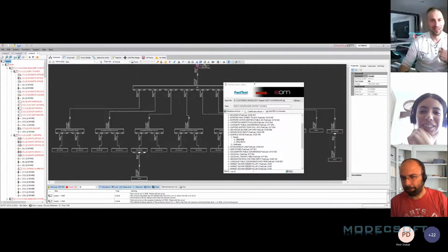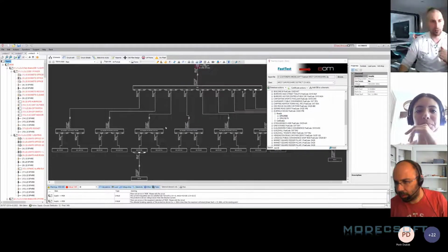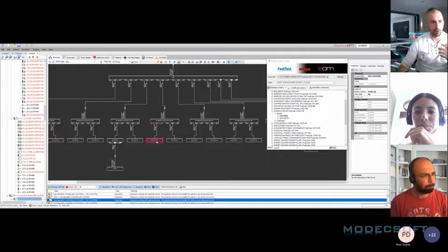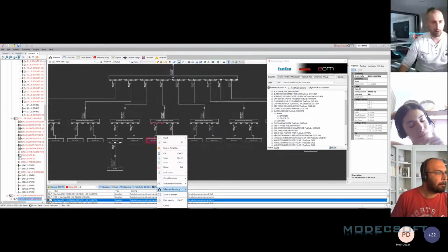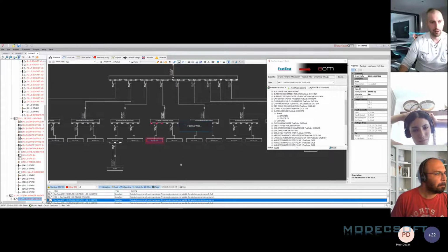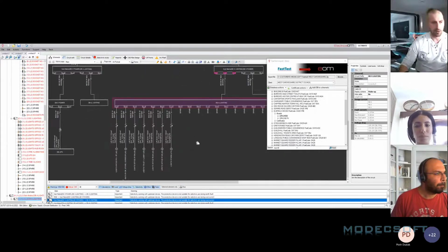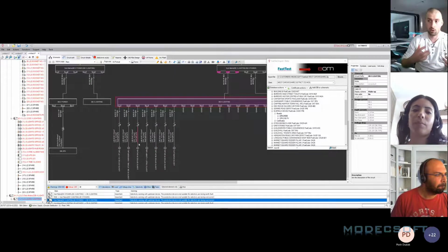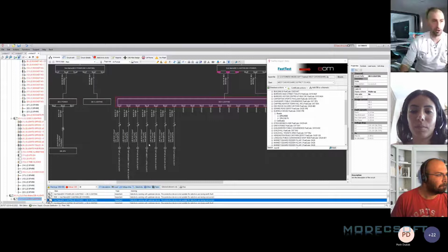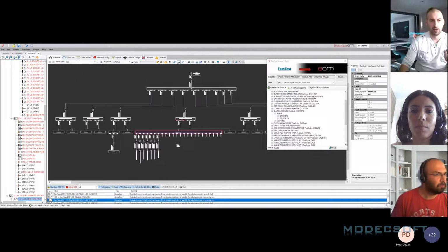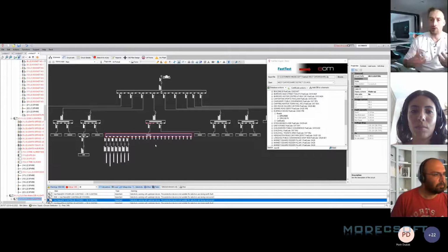Here we go. As you can see, it's pulled in all the information from all the different things here. So we've got lighting and power. Currently, these are in what we refer to as compact mode. If I leave the compact mode here, you'll be able to see the final circuits and things there. It has identified what's a lighting circuit and what's a socket circuit. It's assigned the correct symbols and information, selected all the cable sizes that were put in the report and protective device sizes as well, so you can see all the information.